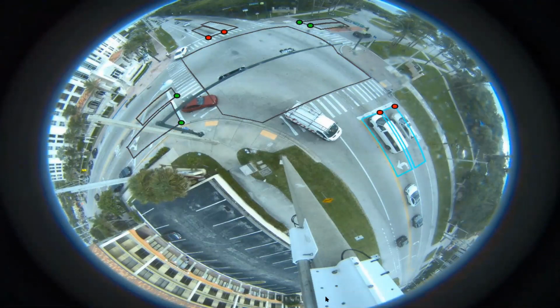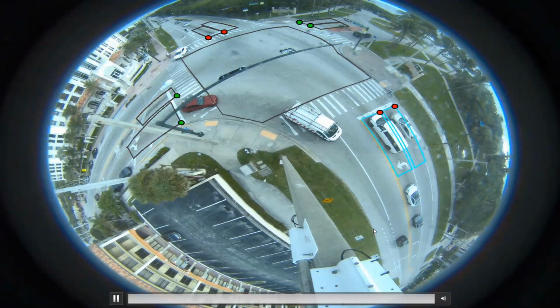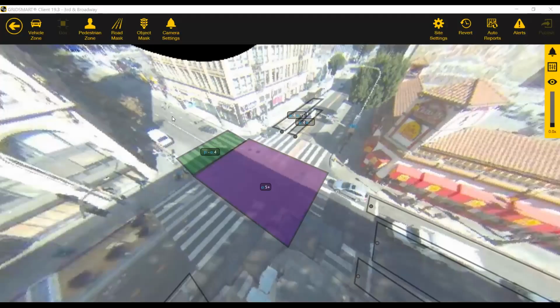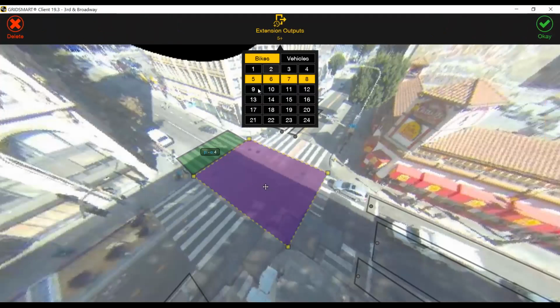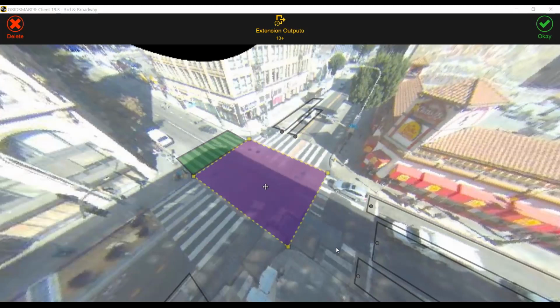Yeah, sure. So basically, the output that's assigned inside the box, I don't know, Justin, can you jump back to the client real quick? And then bring the box outputs. So basically, depending on what you're using, SDLC or this is a Caltrans intersection, so we're only using the 24 outputs. So if I set up 13, 14, 15, and 16, I could set them up on the I and J rack for a 332 cabinet, where I can set up advanced detection and add extensions on the controller. That's how this works. And it will be the same thing for an SDLC cable. It's depending on what BIU you want to use and what outputs on those BIUs, BIU 2, 3, 4, or 1, whatever you want to use for extension as advanced zones. It works like an advanced zone, so you're only adding extensions on your controller. That's about it.